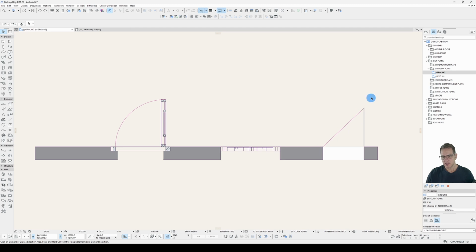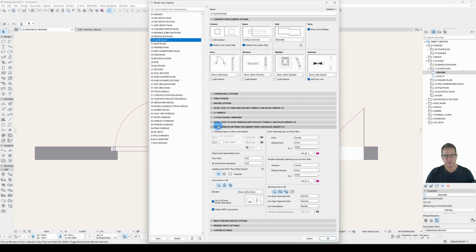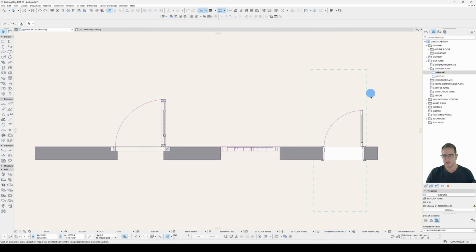Now, granted, that's unlikely to change throughout the project. So if you've got a convention of doing it one way, it's likely going to stay that way for the duration. And the other thing you have is minimal space lines. So when I turn them on, they'll show on the doors that are scripted to show them, but the ones that you have saved using the save as or create from floor plan method, they of course don't have them. So these minimal space lines are attached to the door. They respond to its size. You don't get that with these save as methods.